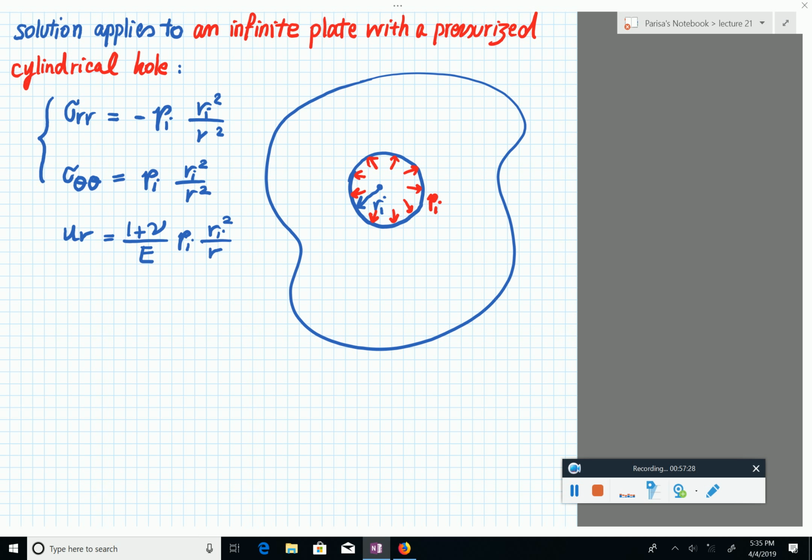Are you talking about the boundary conditions? Yeah, the pressure has to go on the radial axis of symmetry. But typically, pressurized, like for example a pipe, typically it would be really like that, right, after a while. Yeah, so this is a good point. Look at the stress solution. In the denominator you have r squared. So when r is increasing, it's going to go away. And that's why I was showing you, right? The effect is going to go away. So it's going to be smaller. That's given. Yeah.